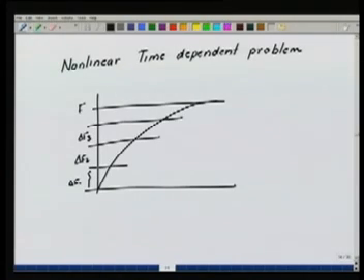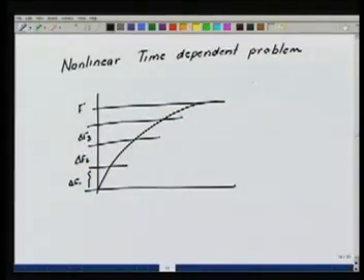Now when I am in a time dependent regime, then I'll have to frame first the semi-discrete formulation with the nonlinear stiffness matrices sitting there, okay, and the mass matrix, if it is nonlinear, sitting there. Okay, then at every time station, so delta t, I am at a time station I minus 1. I want to go to the time station I, okay, using the delta t.